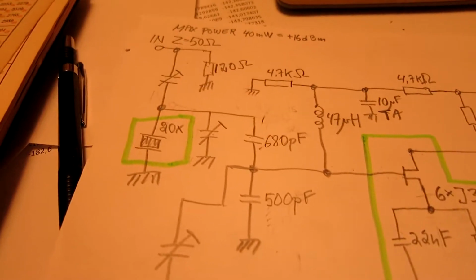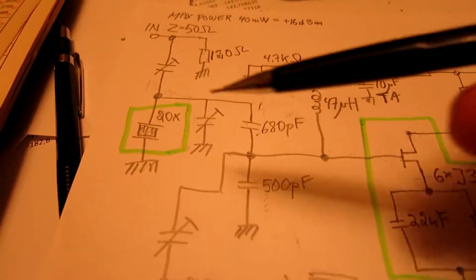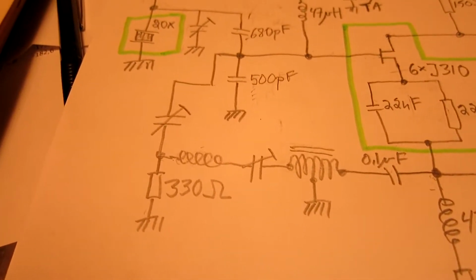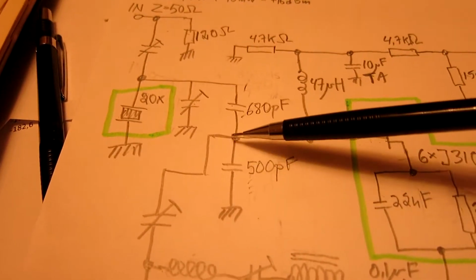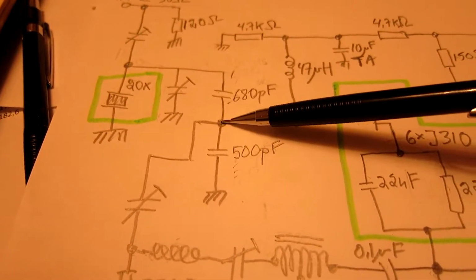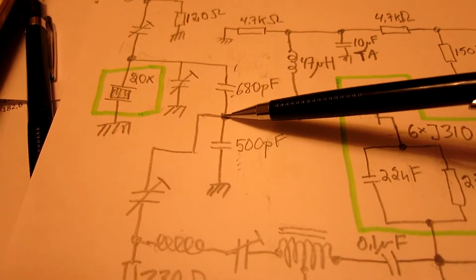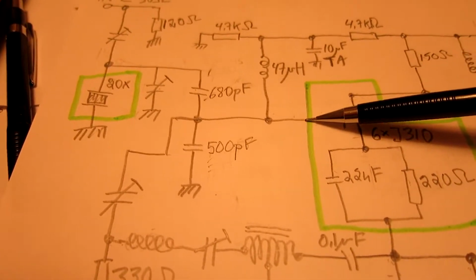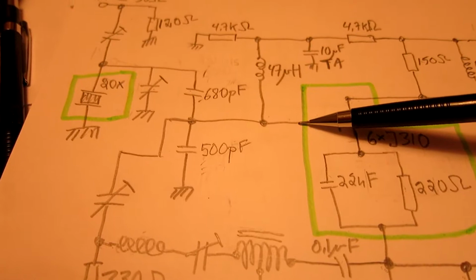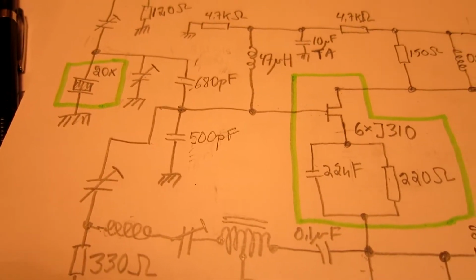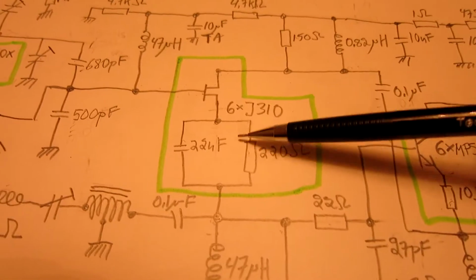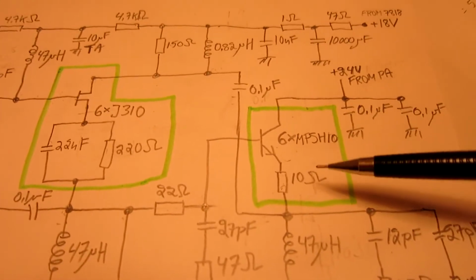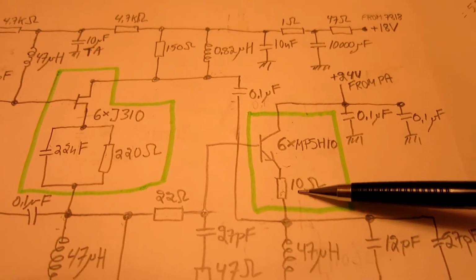In the next video I will reconnect the filter to the amplifier and make sure I tune it properly, because I want the Q of the filter to be still 90,000. Means I don't want a negative impedance or a load from the transistors. I want them to have an infinitely high impedance. I think that is what I want. And then I will look at the noise added by this source follower, and possibly if there is some contribution from this bootstrap circuitry.